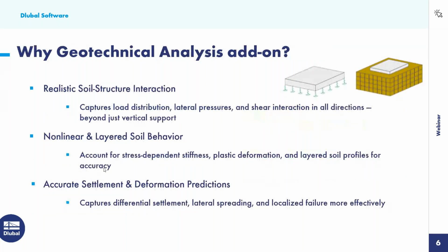So we might be wondering, why would we want to use this geotechnical analysis add-on as opposed to a more simplified approach, where maybe we have a slab type element and, as we're used to in any FEA program, we just apply a spring support stiffness to the base of this element? Well, in comparison, the geotechnical analysis, as we just discussed, will generate this 3D soil solid instead, as we see over here on the right-hand side.